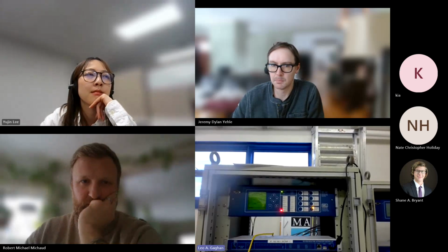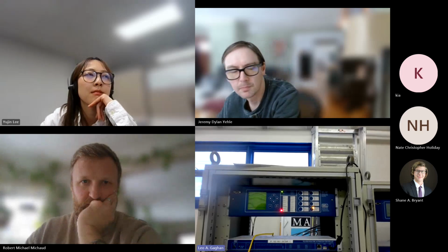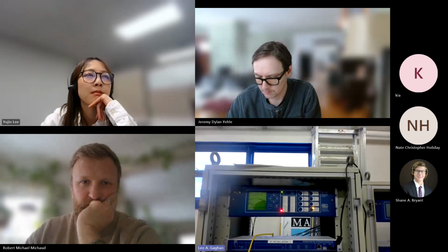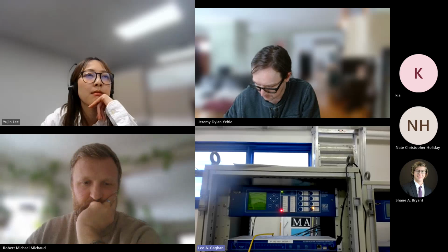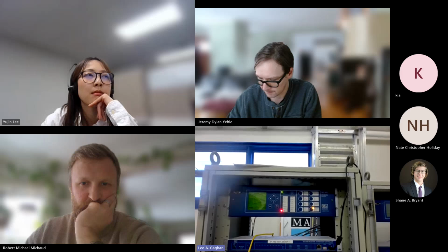All right. So what's behind these bits right here? What is this block? That's a latch. So you can see here, you have an S and an R. S stands for set, R stands for reset. So when you have a 1 come into the set, it's just going to latch. So you can give it just a quick pulse and it'll remember that. And it'll stay that way until you reset it. So when you hold it again for like a second, it comes to this side and it resets it.